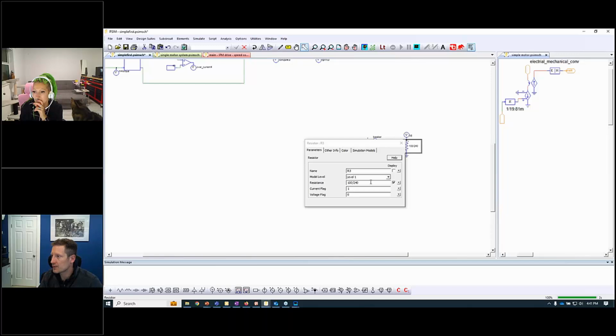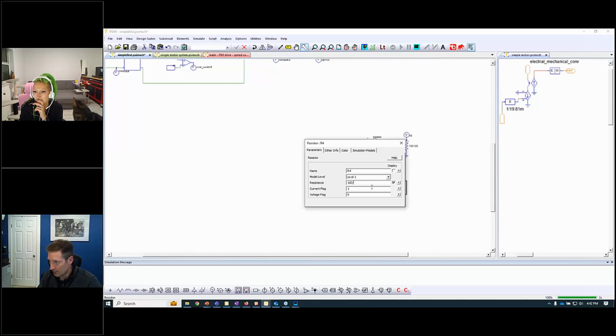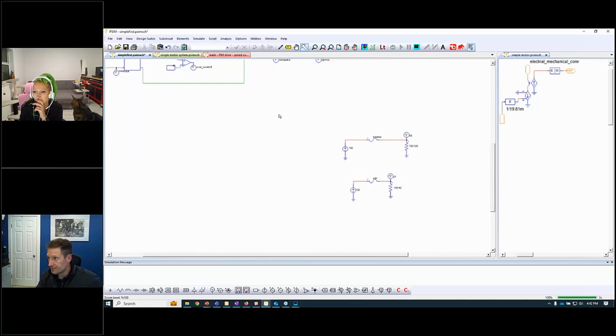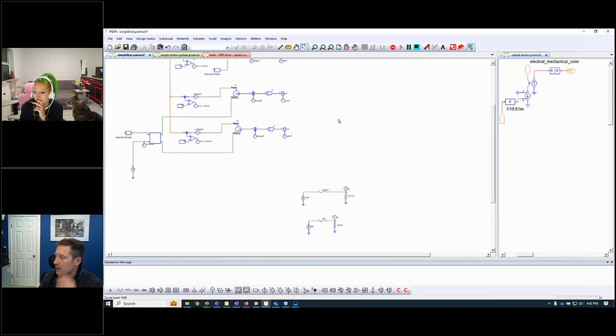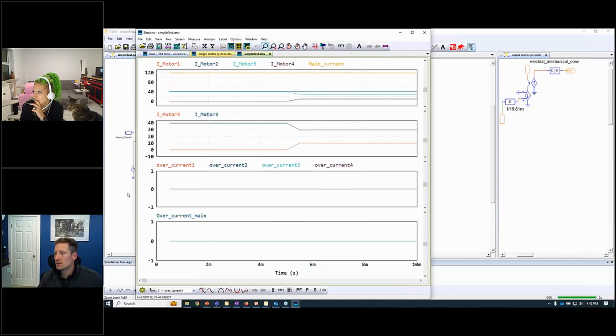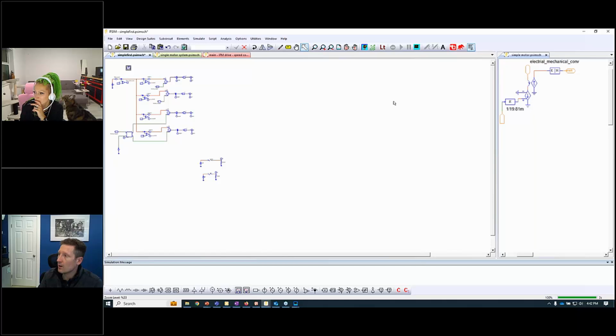What we can do is look to see, the breaker has a rating of 120 amps. So let me just change that to 120, and this one's got a rating of 40 amps. So let's run this. Oh, I'm actually going to run it for a lot longer. We're going to boost up the time step to 1 millisecond, and we'll simulate it for 200 seconds now.